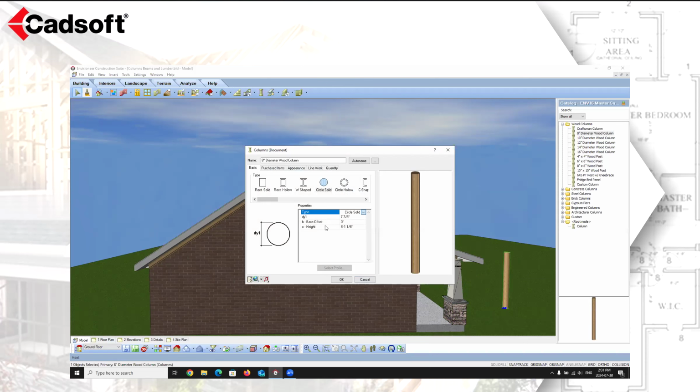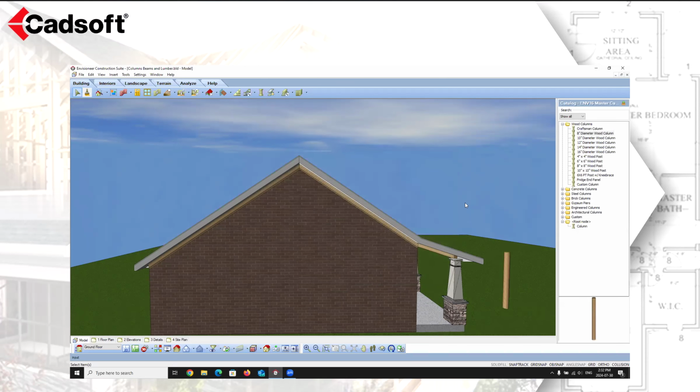These columns, again, can be set to whatever the value of the building locations are. You can also adjust these manually. So if you want it to be an actual 8-foot column, you can type that in. Columns can be created by selecting one of the preset shapes or by importing custom geometry in a variety of different file formats. We then looked at members and how we can insert members to match the plane of a previously inserted surface, how we can apply a ply beam in our design using the advanced members tool, and how to insert just individual members that we would use to run in our designs on a vertical plane. Or sorry, on a horizontal plane.